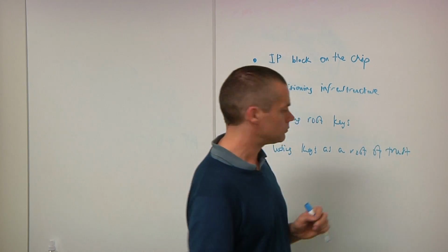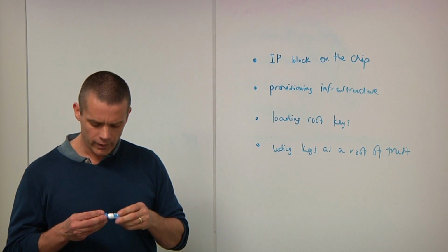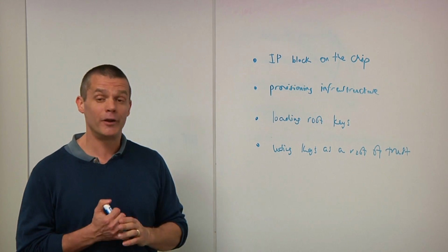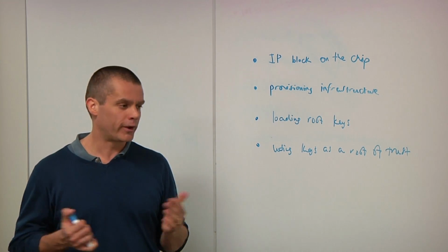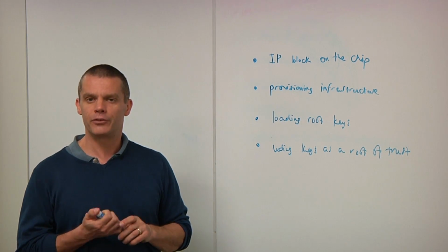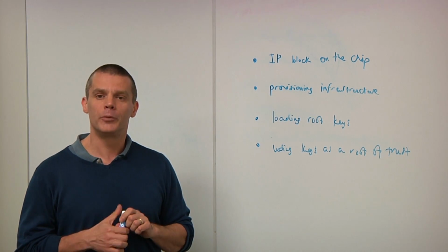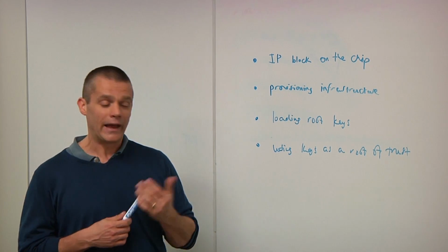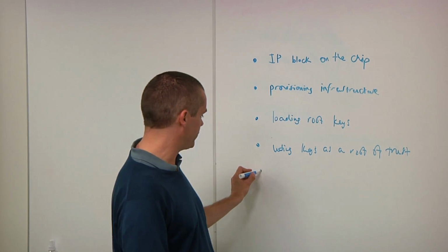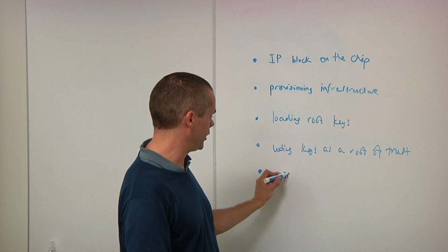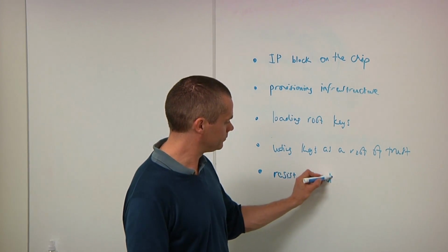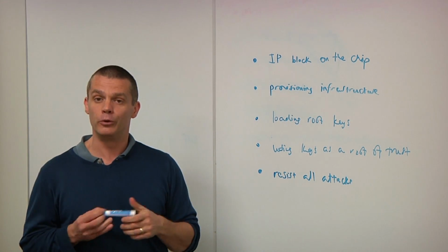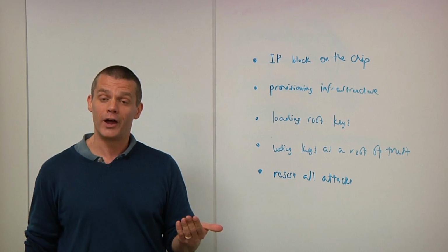What's the power performance overhead on something like this? There are a number of different ways to look at that, and a number of different options you can choose. From a gate count perspective, you're talking about roughly 1 to 300,000 gates on the device. From a power perspective, not typically material to the power profile of the device. And from a security perspective, it's crucial to understand that this has to really resist all attacks. We talked about the TEE as a pure software solution designed to prevent software attacks, and that's not enough going forward.